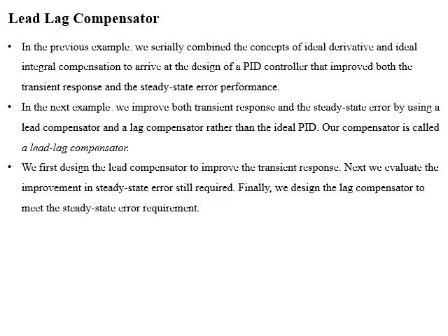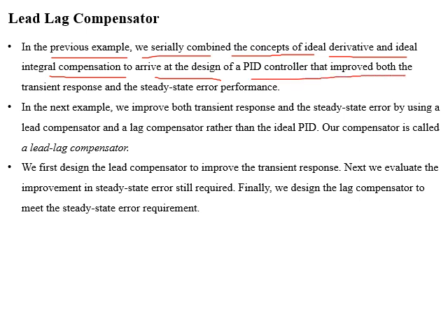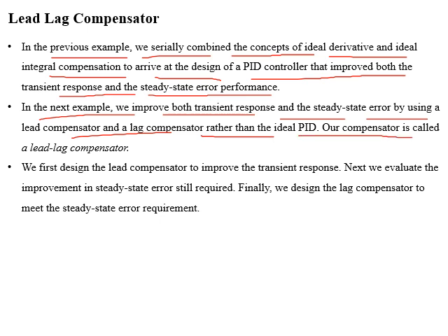Dear students, in previous example, we serially combined the concept of ideal derivative and ideal integral compensation to reach the design of PID controller, which improves both transient response and steady state error specifications. Now we will study how to improve both transient response and steady state error by using a lead compensator and lag compensator rather than the ideal PID. Our compensator is known as lead lag compensator.